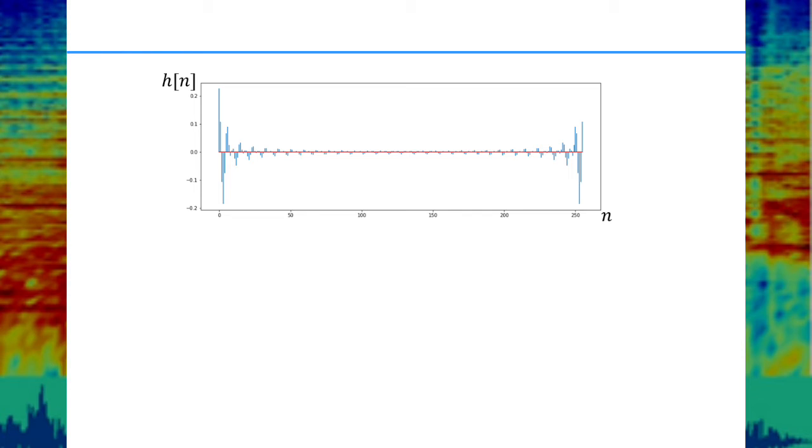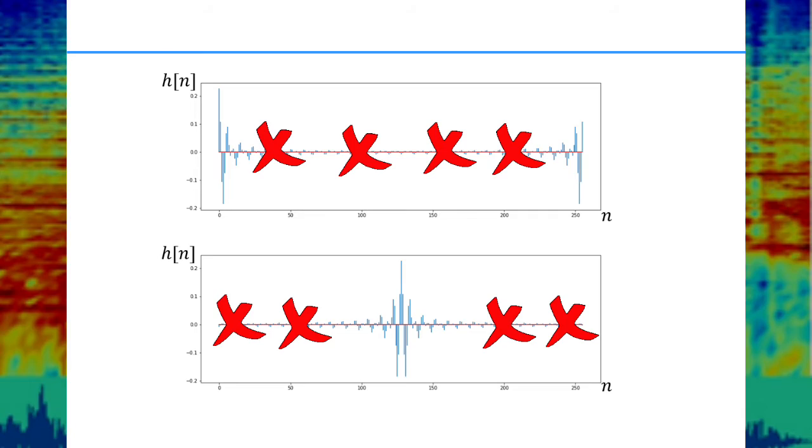First, we get an impulse response of 256 non-zero values, that is, 256 non-zero filter coefficients. In many cases this is undesirable for real-time performance or quality reasons. We therefore want to limit the length to, let's say, 20 to 30 non-zero filter coefficients. Second, we observe the consequence of the circular nature of the DFT, because the impulse response coefficients for negative n are found at the tail of the computed inverse DFT. So the actual impulse response that we're looking for is this one.